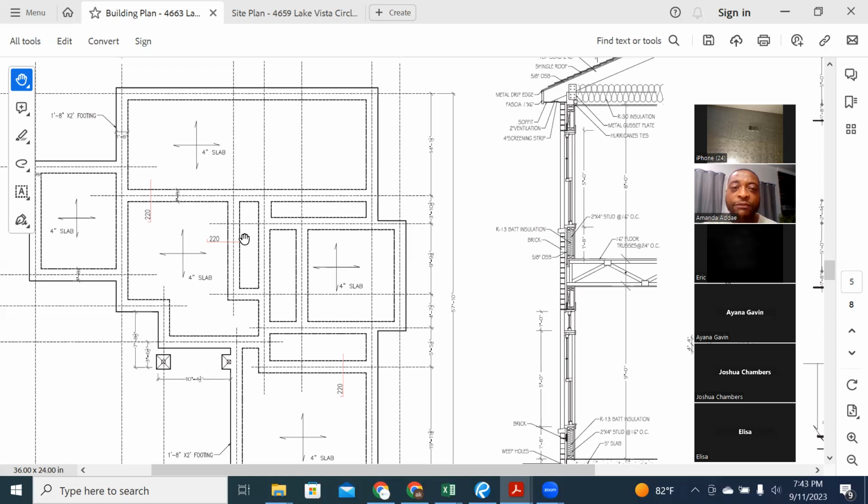If you look at our video, you will see that in action. You will see that when the first 3 trucks came, they poured the footings. The first truck did like a third of it, the second truck did another third, and the last truck did the final third of the footings. And then the rest of it was to do the slab. So that's what they call a monolithic pour. So when they say that to you while you're out in the field, understand that's what they mean. They're going to pour both your footings and your slab simultaneously.